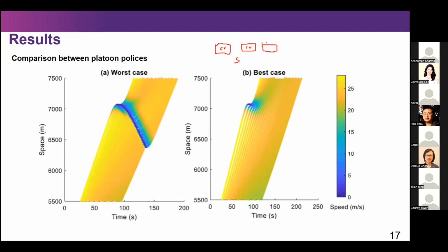If I want to pass this information to this particular follower, then I have to think how the human driver will differentiate between the speed of the first leader and the speed of the second leader, right? How will we communicate this scenario? Because of that, whenever a connected vehicle is ahead, then only my follower will be benefiting from the information.